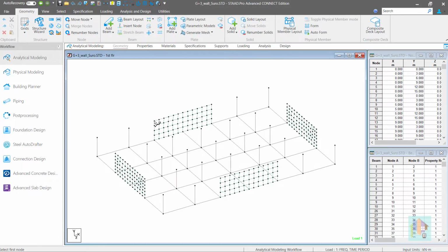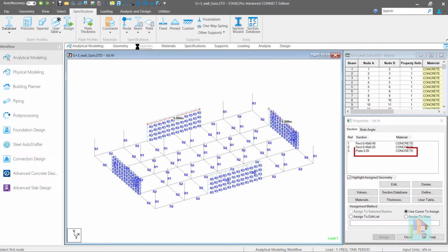Length of wall along X direction is 9 meter each, and along Z direction is 8 meter. Thickness is 250 mm. We need to consider the wall area along the load direction. When seismic force is applied along the X direction, these 9 meter walls resist that lateral force, and when load is applied in the Z direction, 8 meter walls are used.